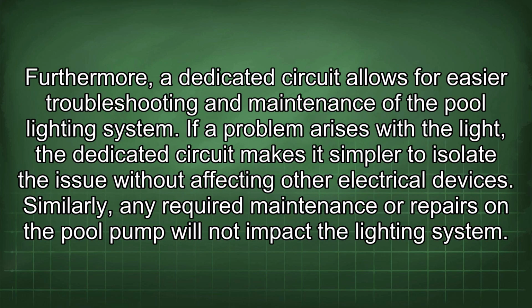Furthermore, a dedicated circuit allows for easier troubleshooting and maintenance of the pool lighting system. If a problem arises with the light, the dedicated circuit makes it simpler to isolate the issue without affecting other electrical devices. Similarly, any required maintenance or repairs on the pool pump will not impact the lighting system.